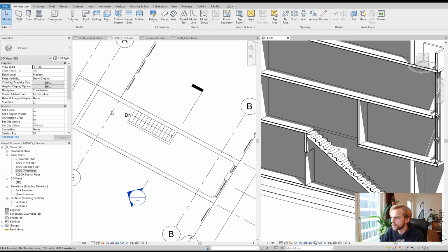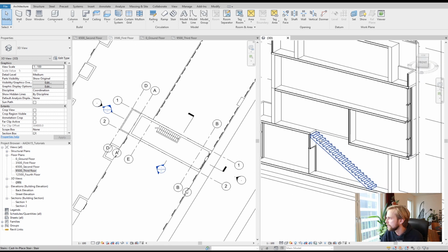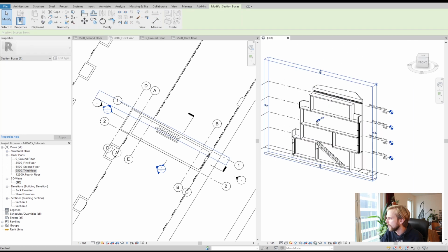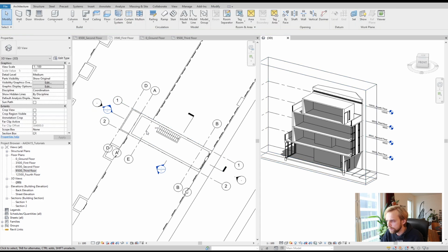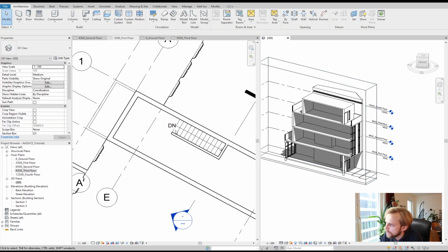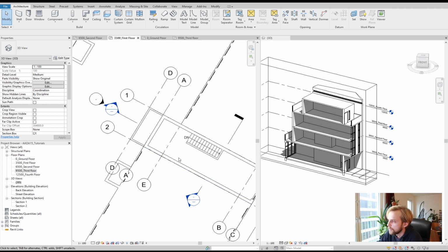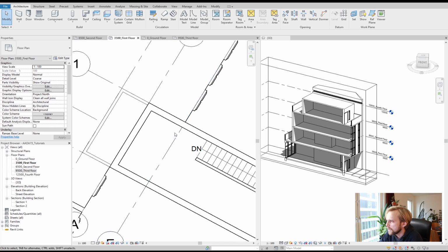It would probably be some sort of a... Actually, let me just show you, just so that you get a sense of how I'm thinking when I'm doing these things. So you arrive here, right? That's your arrival point in the 1st floor, from the ground floor. Then you choose to either go up again or to go into this space, right? So it makes sense to have a staircase winding around here, doing a U-shape wind here.